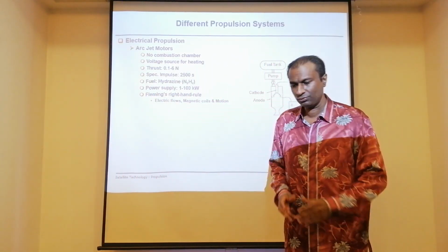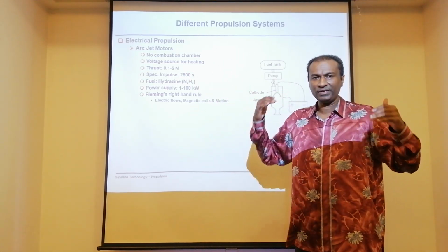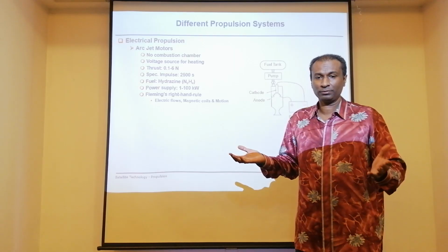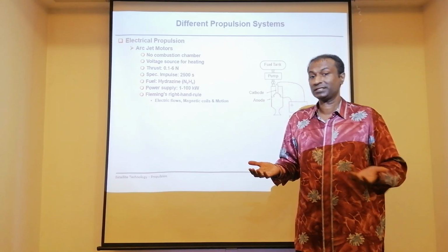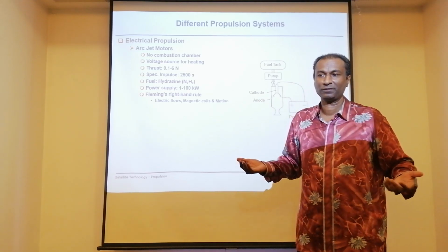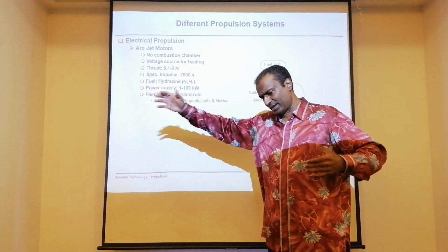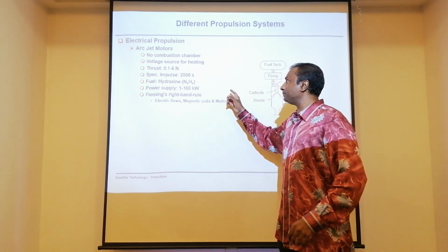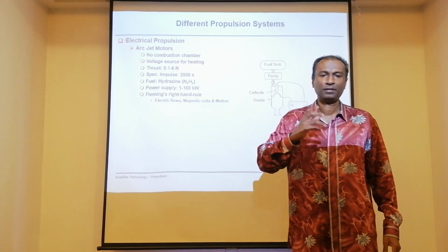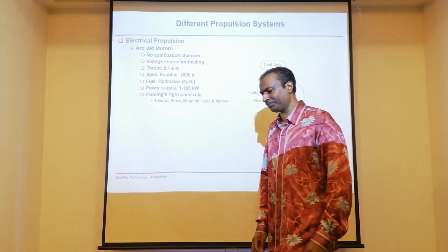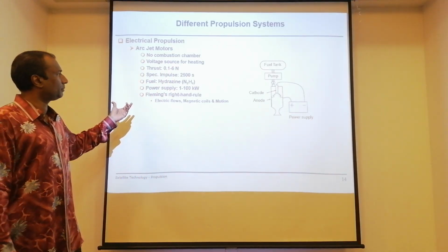So when you do an interplanetary mission, you need to travel very far. Therefore, your delta V needs to be quite a lot. So in order for us to have a high delta V, one of those ways, technically speaking, is to have a very high specific impulse. You have seen it in the formula. So when you want to fly very, very high, that's the reason satellites or rather spacecraft with electrical propulsion you see very, very commonly in deep space missions. Okay, Deep Space One, for example, is a mission. So you have all these electrical propulsion systems.